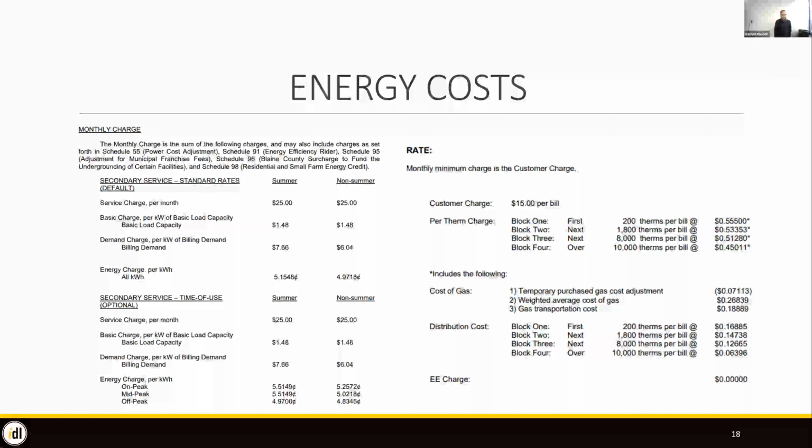If you say, well, it's on average 7 cents per kilowatt hour, the code official, it's up to their discretion, but they can require you to put in the actual rate tariffs, right? Which differentiate based on summer or winter. And then the energy charges vary based on whether it's on peak or off peak. And then you've got different demand charges. The energy model can do all of that. It might be a headache trying to do that if you weren't using an energy model, but this is for energy modeling. But you do have to be careful that you build in the current rates for it.